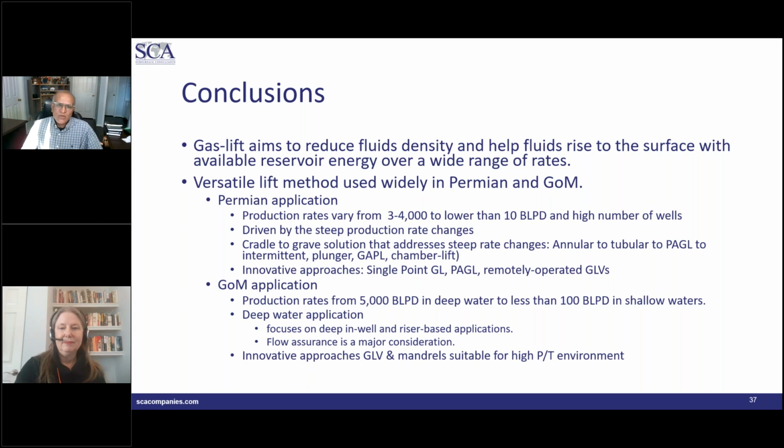Yes, so in the Permian, one challenge that I have heard from operators about is paraffin or wax deposition. As the injection gas expands and there is some cooling going on, operators are looking at what to do about the paraffin deposition. Of course, you can go for hot oiling, but that means disruption of the production. So there are some approaches that people have tried to alleviate this challenge.